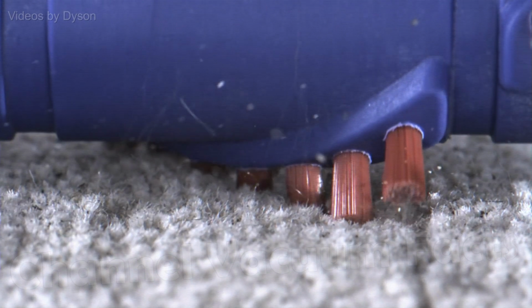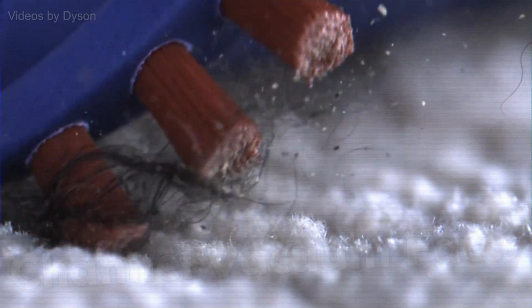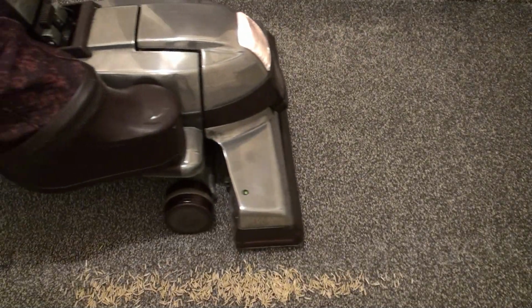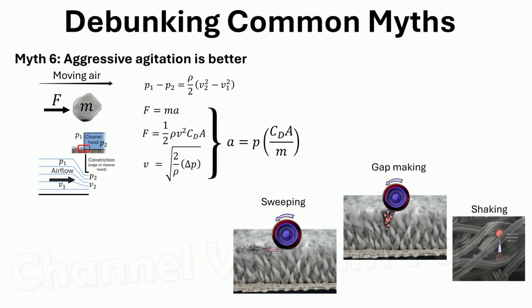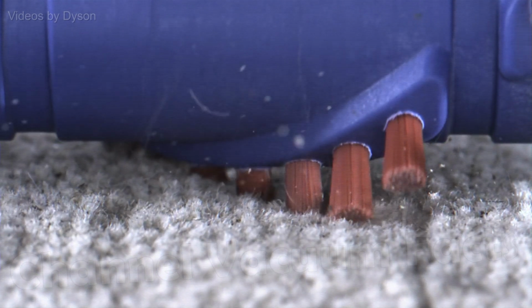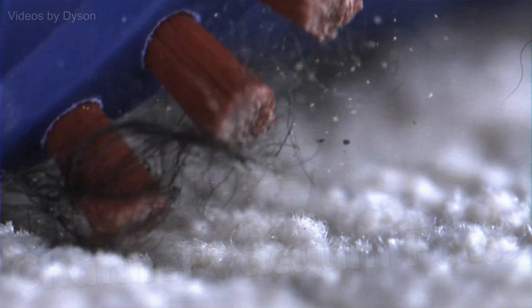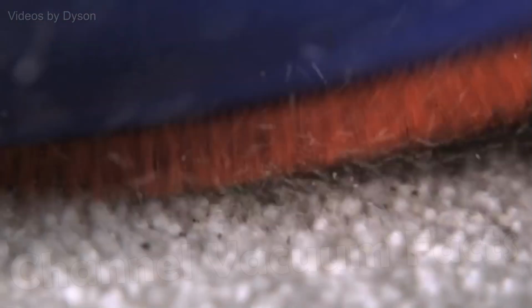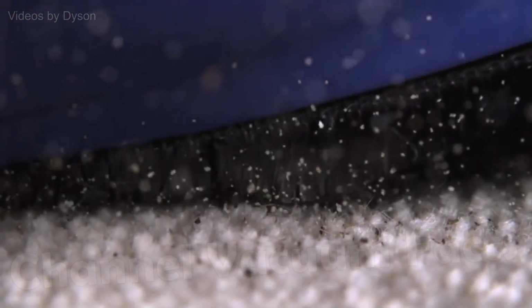A common myth is that violent, very noisy vibration is beneficial to cleaning performance. Visually impressive particle bouncing outside the cleaner head is used to imply that cleaning performance under the head is improved. As discussed earlier in the agitation section, this is false. High suction and pile separation of fibre jostling result in the maximum airspeed used to accelerate particles. Extreme vibration is usually a result of poor design, where the bristles on brush bars protrude too much and physically impact the carpet too strongly without contributing further to pile separation. This at best causes a lot of noise, and at worst can wear carpet more.